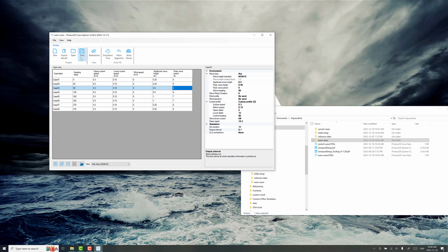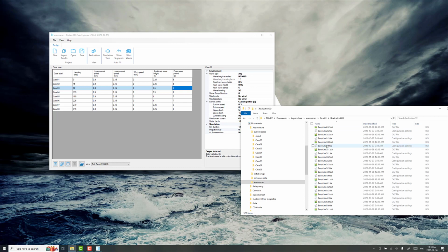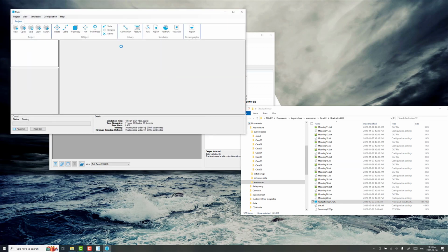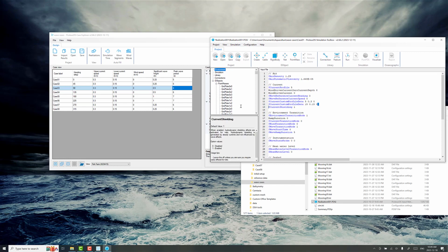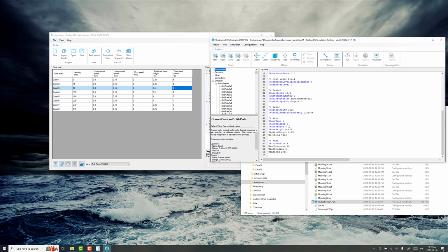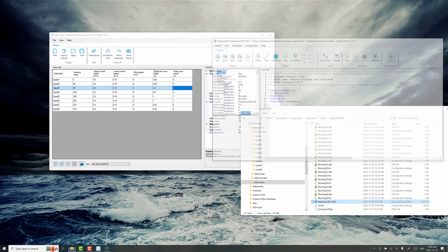Now what we do is just save this, and it's never a bad thing to check. Just take a quick look. You can open the simulation toolbox files if you like, and just verify what you're seeing in there. There's the current profile and the associated depths and the heading. That's what we want. And we've got a wave period of 5. Now this is going to be 1.9 times the 0.25 significant wave height, which is good. And everything's looking good. We've got a simulation output rate of 0.1 and just 10 seconds of simulation, because that's 2 times the wave period. I think we're looking good.